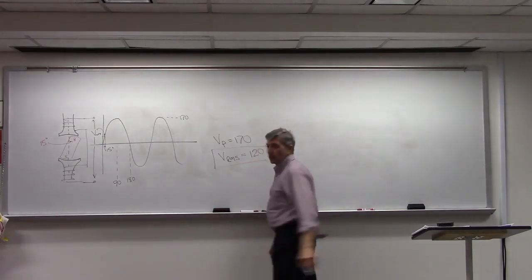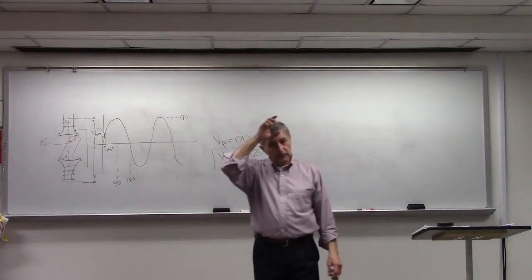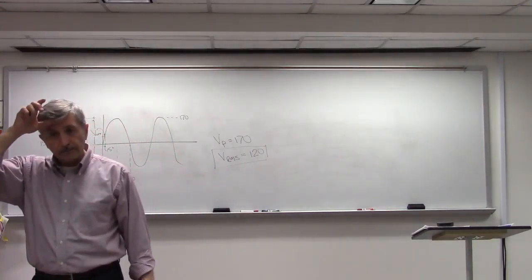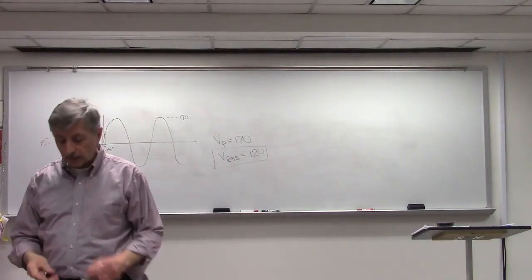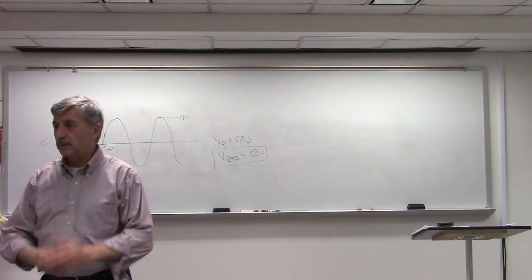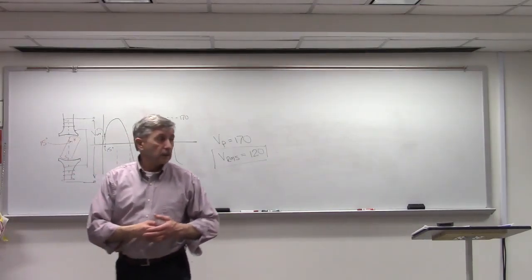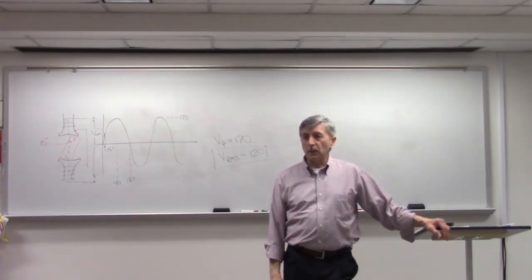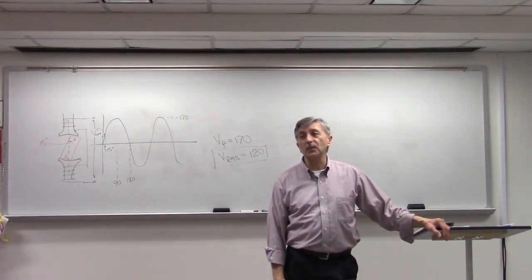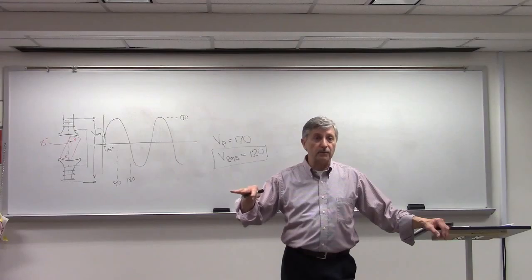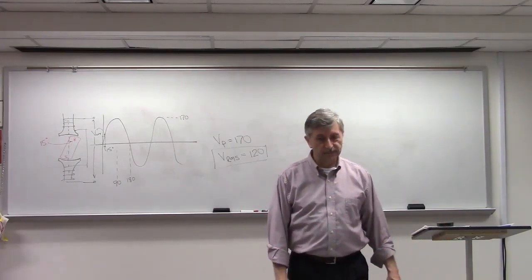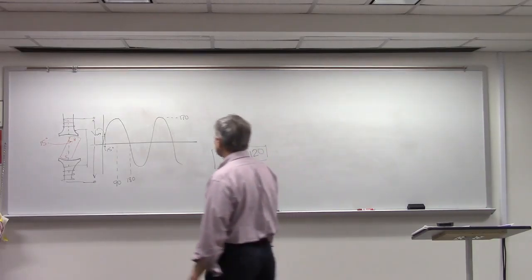And that corresponds to a standard duplex receptacle. If you've ever been shocked sticking your finger in a receptacle or working on something when you thought it was dead and it isn't dead, and I've been shocked more often than I care to admit, you're exposing yourself not to 120 volts, you're exposing yourself to 170 volts. And it's a little bit of a kick, okay? A little bit of a kick.